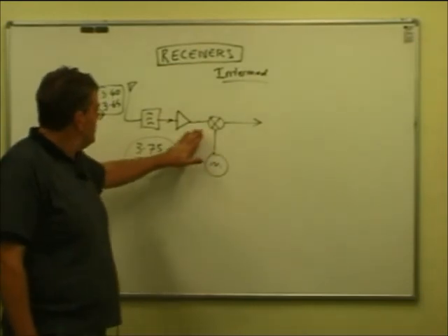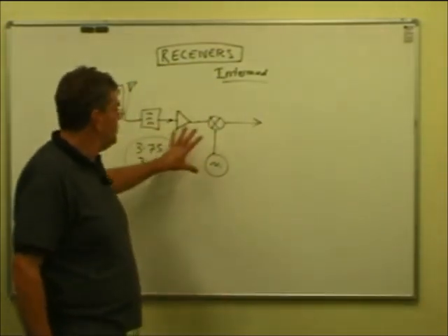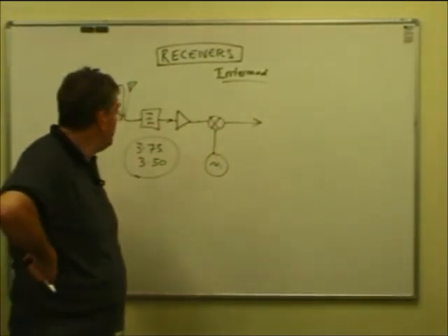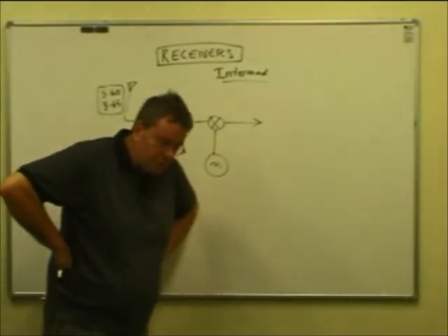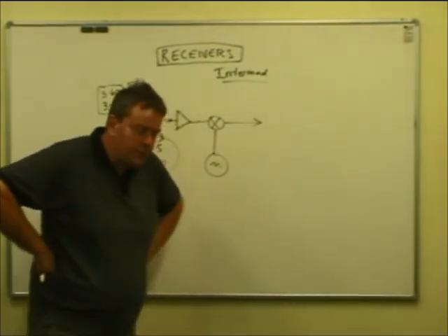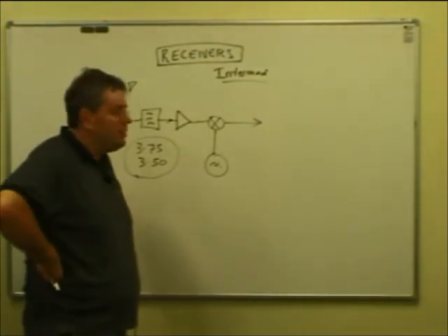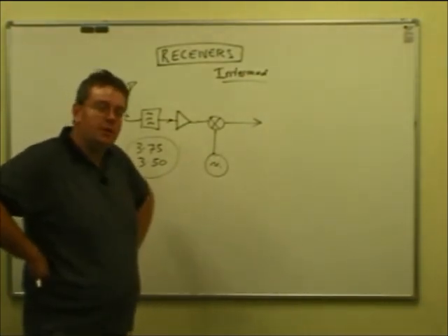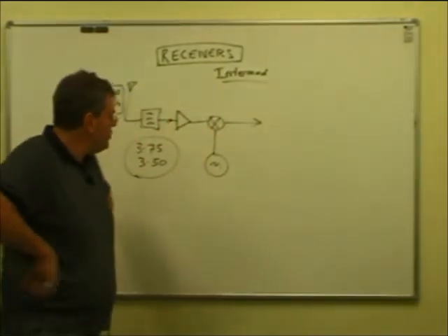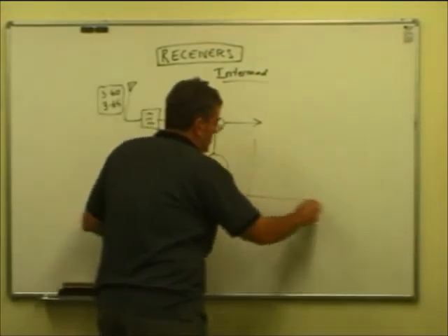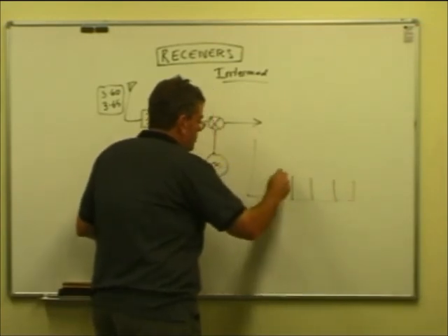Modern receivers are designed, the mixer and the amplifiers quite well, especially the high-end, really high-quality stuff. They put a lot of design work into the front end of the receiver to get around that problem, because that can be very significant. And you do see it if, say, there's a contest on the amateur bands, and you're working on the 20-meter band, 14 to 14.3, around 14.2, 14.25, and a bit below, maybe 14.15, right up to 14.25 and beyond. And there's a whole lot of very strong signals on the amateur band, people calling all around the place, maybe stronger than that.